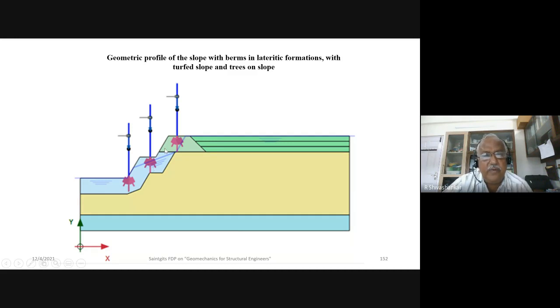And also, whenever there is rain, the leaves of the tree will take the impact and reduce it, so you will not have any gullying on the top of the slope. And also the roots will absorb the water. So when they absorb the water, they create suction. That's what I said in unsaturated soil mechanics. The suction is a very important thing. Whenever there is suction pressure inside, the shear strength of the soil is increased, right? And also it reduces the flow, the impact of the flow.